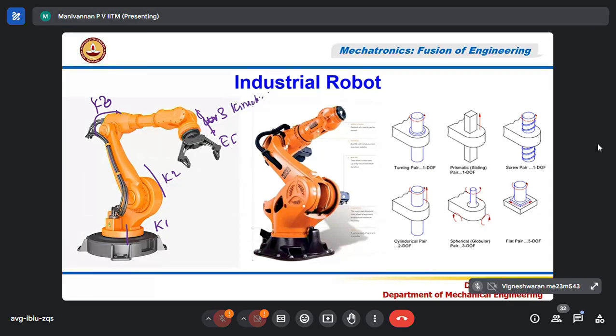The ball socket looks like two parts, but actually it is like three mechanisms, one after another. All are rotary joints, and finally the end effector is connected to it, as if three joints having a common point of operation or center of location. So the wrist mechanism provides three links.